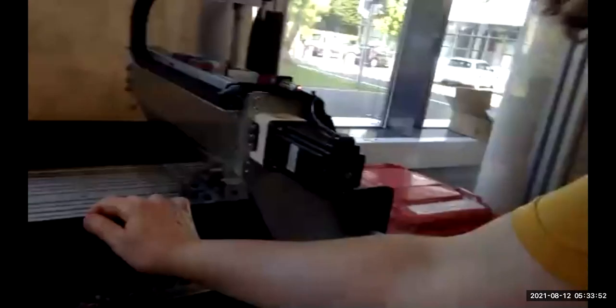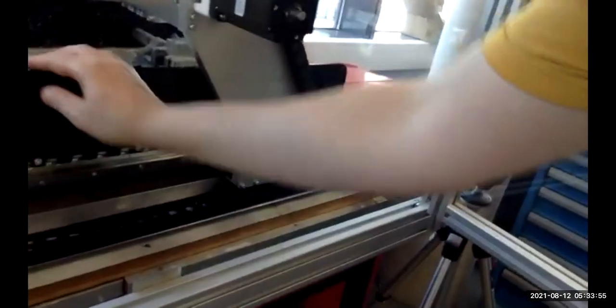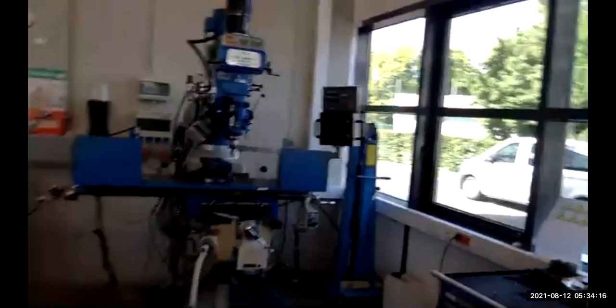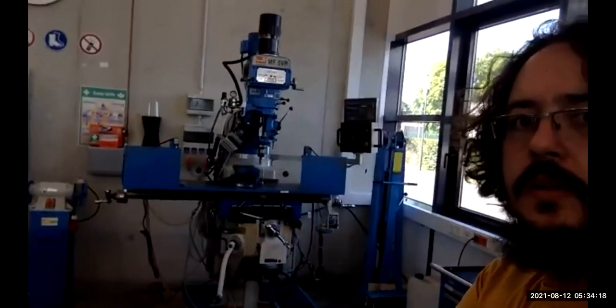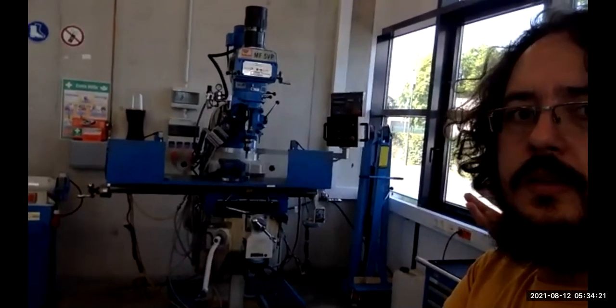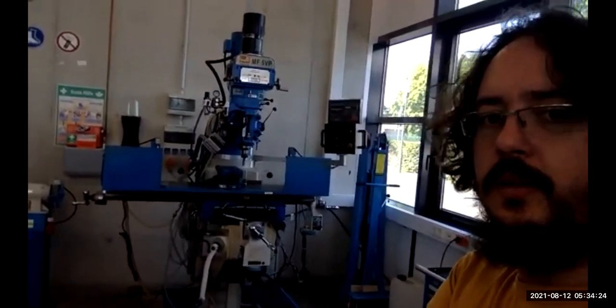Another problem that this machine has is that the protection that I laser cut here is not enough to protect the guides from aluminum. So now they have aluminum on them. We need to improve this system, because otherwise the guides will wear once you have the chips. So we're going to make a recycling system. There's a big mill behind us here, and we're going to use the same cooling system that it has. So the flow comes right over the head, and with the liquid cooling, the swarf is no longer going to get under the rails.